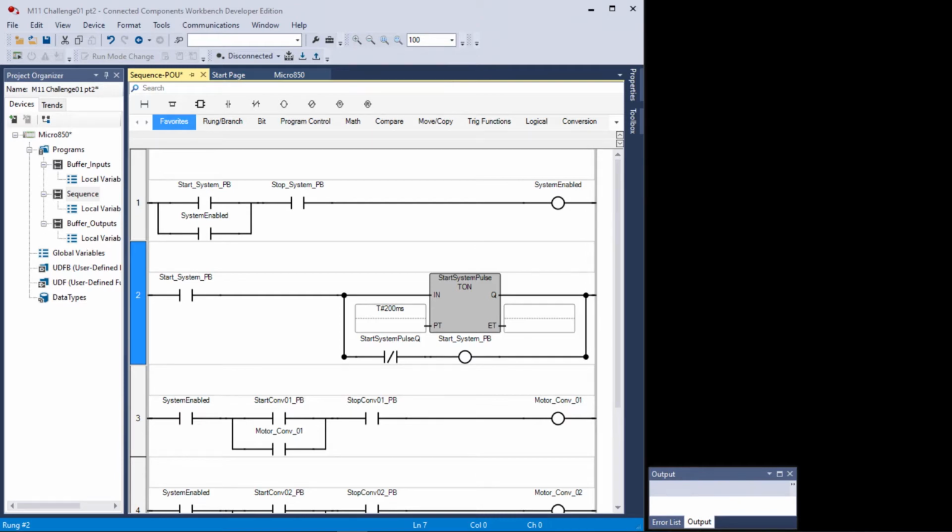This is somewhat scan dependent logic. The rung won't work unless it sees that true if on at the head of the rung is true to see that the timer is timed out, and then it does the false execution on start system push button, and the next time it comes around, the last thing it heard was that you're off. So start system push button, that bit memory is off. This is self-extinguishing logic.